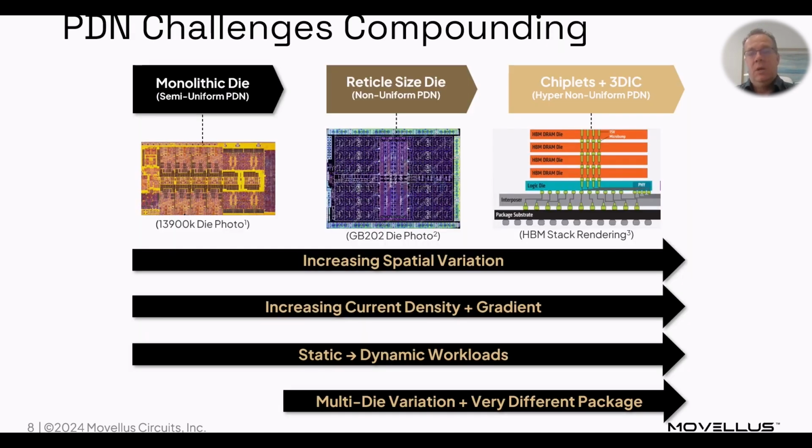And you're having to simply raise the supply because you're having some paths fail because your nominal was too low. Also, we need to consider the packaging and context for the chips themselves. Single monolithic die, the traditional single piece of silicon in a single package, has the challenges we've mentioned so far. These die in themselves are getting bigger, larger, and have different process temperature characteristics across the die. So for a given core copy that you have arrayed throughout your ASIC, you may have significantly different performance, temperature, process at various corners or various locations on your die. Therefore, you may need to optimize your Vmin on a per location basis.